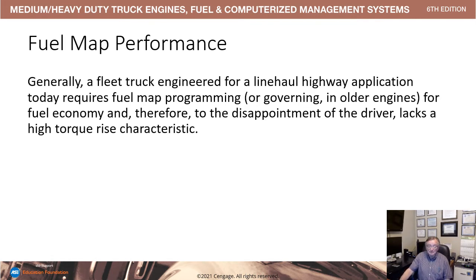Fuel map performance. Generally, a fleet truck engineered for line haul highway application requires fuel map programming, or governing in older engines, for fuel economy. Therefore, to the disappointment of the driver, it lacks a high torque rise characteristic.